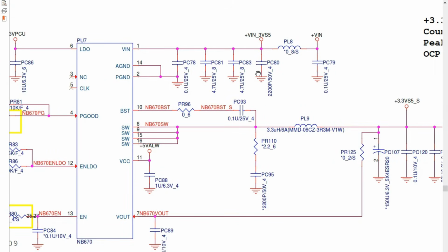That's why you should never get a shorted capacitor. If you check any ceramic capacitor in the motherboard and you get a short, a low resistance, a continuity or a buzzer, it means in that circuit there is a short circuit.